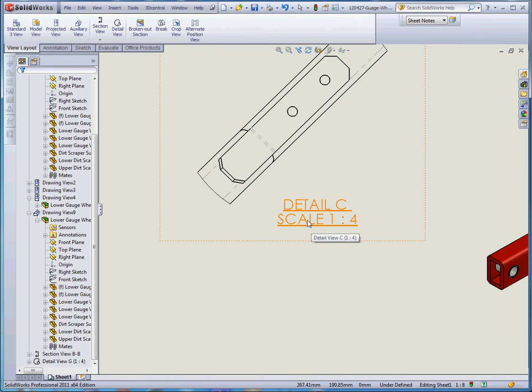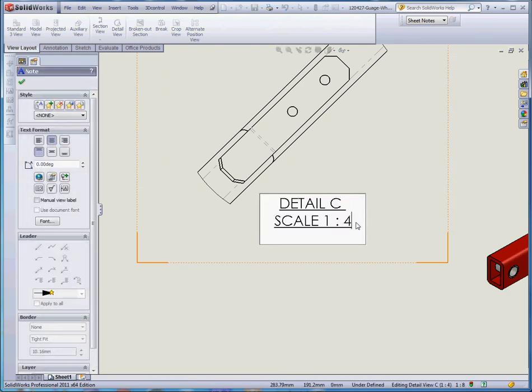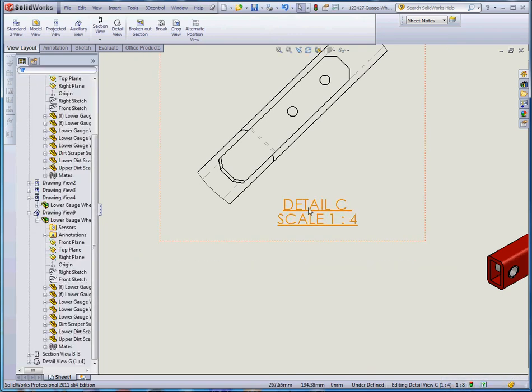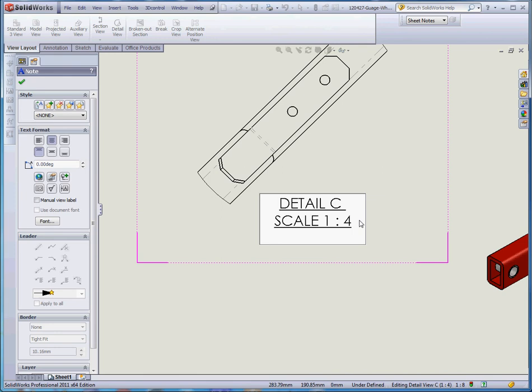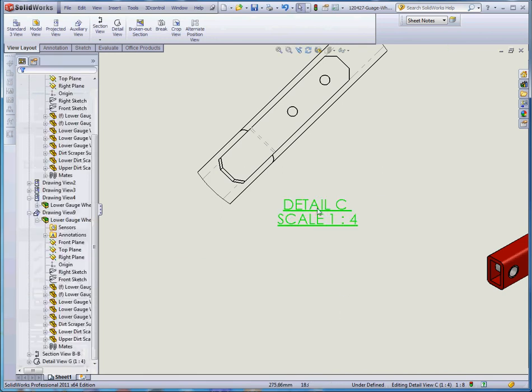So let's do this. Let's go ahead and double click on this, and let's add a note to this. And make sure you have it all capitalized. We're going to call that note 1. And sometimes they put brackets around this, it kind of stands out a little bit better. It also makes it denote that maybe it's a secondary feature out there, something secondary to consider. But I usually see brackets, so let's go ahead and stick with that notation. And, oh, what happened to that? Okay, brackets, note 1.